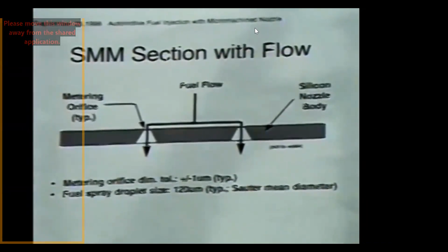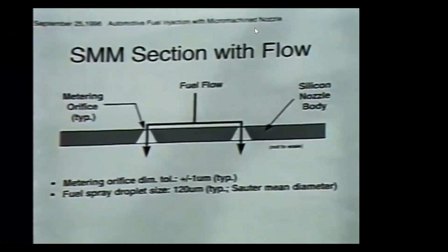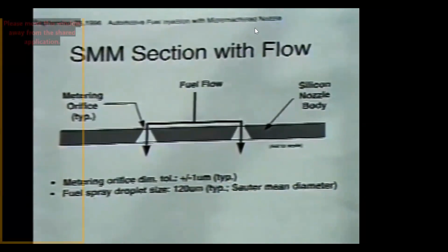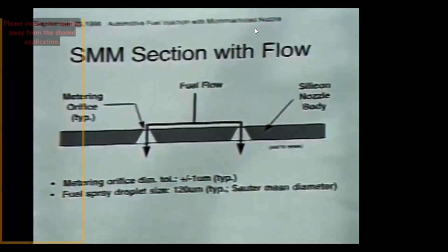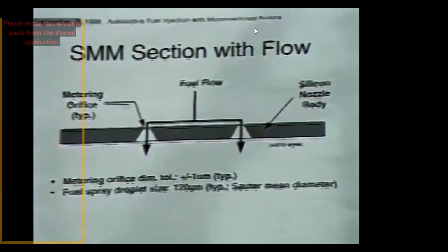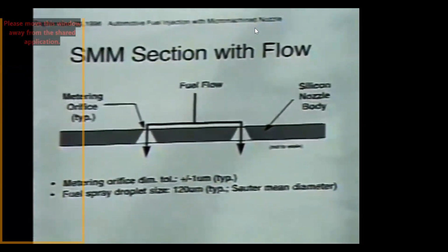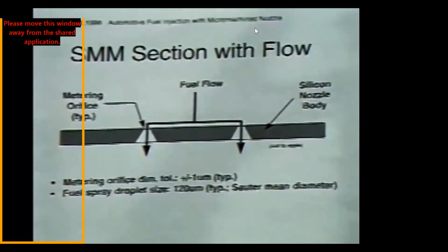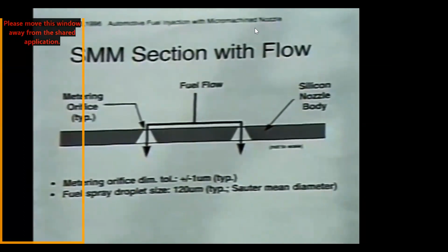The third thing, which is not shown here, is deposit resistance. The intake environment of the engine is a hostile environment, and basically you need to have something that resists the amount of foreign material that attaches itself to the injector. This prevents the clogging of an injector and the reduction in flow.